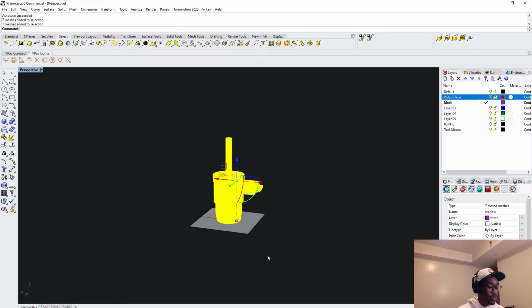Now we need to join the meshes. When we click on the KUKA PRC core component, it will ask for a tool. And once we put in a custom tool component, the custom tool component will ask it to be a joined mesh. In Grasshopper, you can join it through mesh join. In Rhino, it's just a simple join command. So we're just going to type in join. It's going to join it into one closed joined mesh.